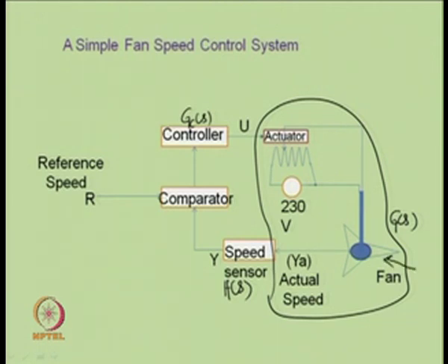Those are known as static load disturbances. Similarly, in the case of inaccurate sensors, we might get noise in the sensor. Those are known as sensor noise, due to imperfection or drift in the components used in a sensor.